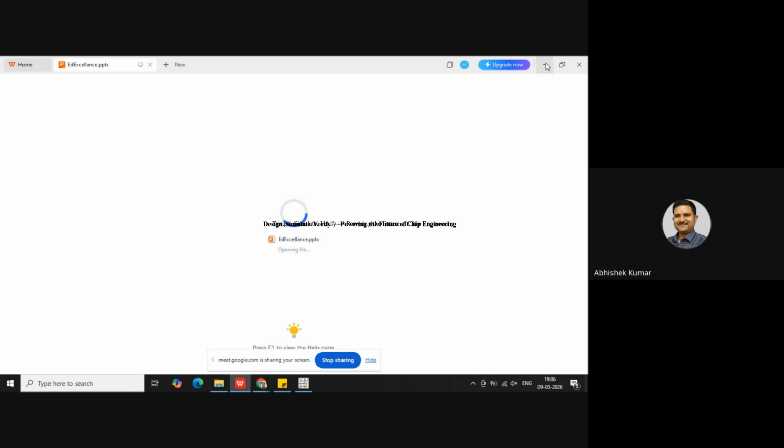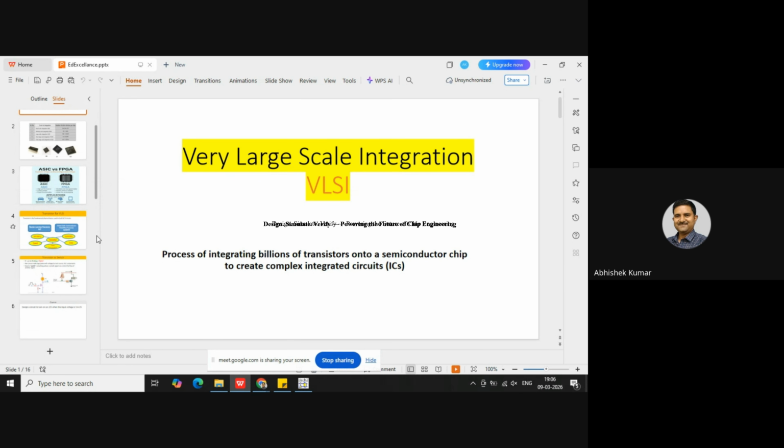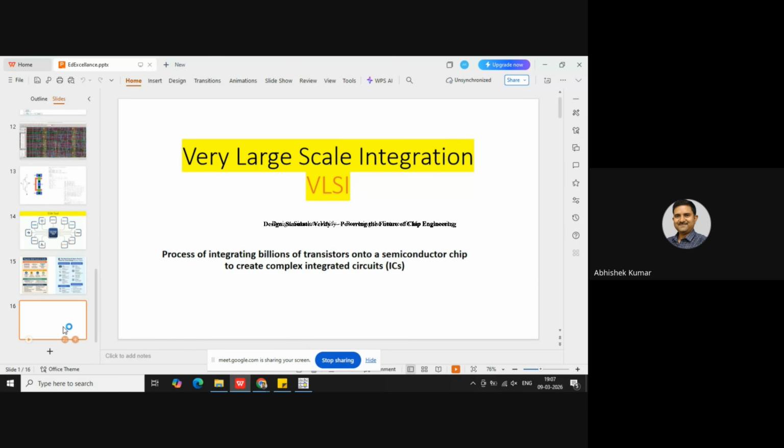Can you guess what this number 1247 is? In digital electronics or digital design, this is a very interesting number. Min terms 1, 2, 4, 7 represent the equation A XOR B XOR C. That represents the sum equation of a full adder as well as the difference equation of a full subtractor. This is a very simple way to remember them.